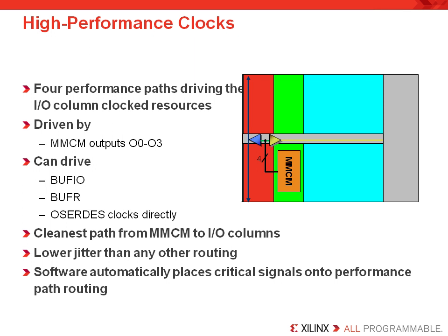And that's necessary in the case when we're driving our local I/O or SerDes resources with a clock generated by the local clock management tile. Now, these performance pads are used when a clock signal is generated from the local CMT and drives a BUFIO, BUFR, or a SerDes resource in the same clock region. Now, the implementation tools will use these fast routing resources whenever necessary.